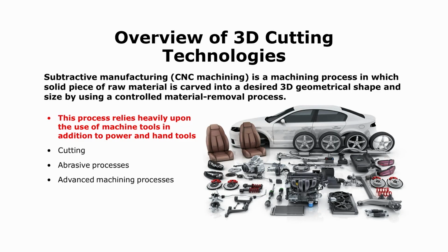Subtractive manufacturing relies heavily upon the use of machine tools in addition to power and hand tools. Typical processes which are part of subtractive manufacturing include cutting, abrasive processes to make sure the surfaces are finished to the needed levels, and advanced machining processes where certain notches, holes, curvatures, high surface points and other details are needed in the product.